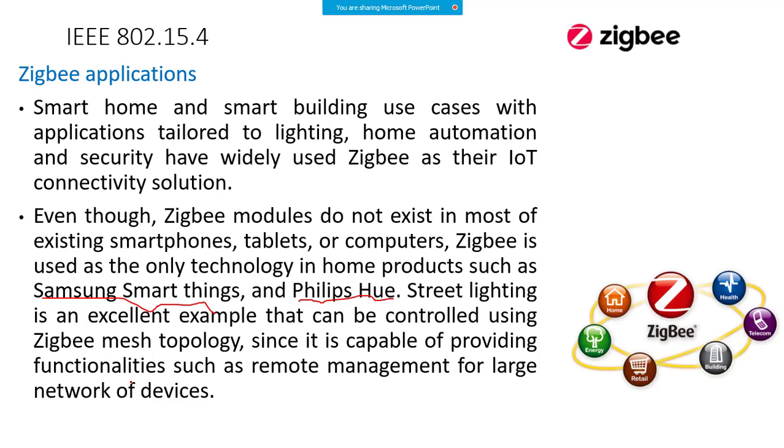I will explain you. Now, please understand, when you are using Zigbee kind of devices, right? For example, let's say we have one device over here. Let's say a bulb from Philips, like here, right? Now, if it has Zigbee, it has to be connected with some gateway. For example, my Raspberry Pi board or my Arduino board could work as a gateway, and then that gateway gets connected to the internet. So this bulb has to be connected to some gateway, and then the gateway will connect it to the internet. So that is how this bulb, which has a Zigbee interface, can communicate with the internet or some cloud platform via a gateway.